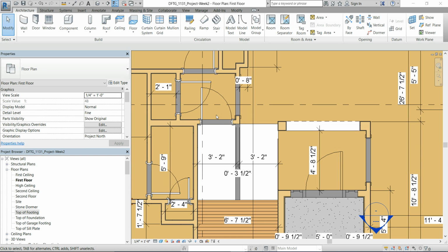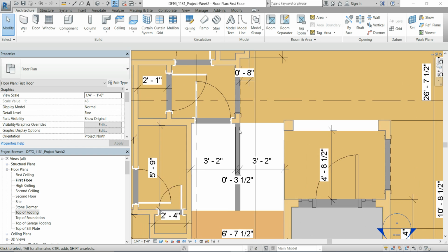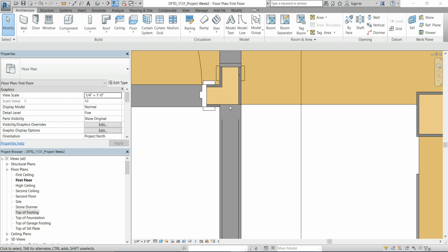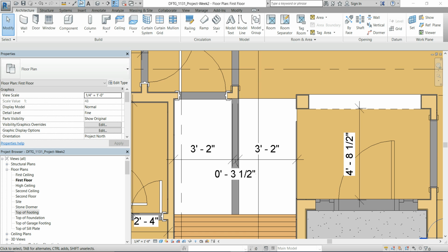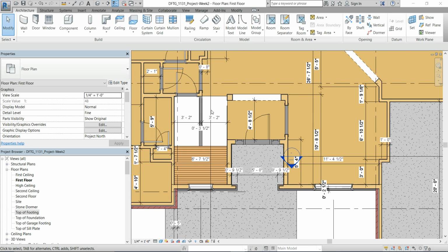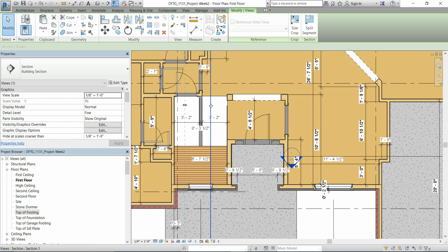All right, this wall on the first floor level was kind of sticking out long. When I created it, I just left it long because I didn't know how we were going to deal with that. I basically dragged it back to the edge of my floor opening. And I took my section view that I'm going through right here, and I pulled the depth of it back so all I see is what's in the stair opening.